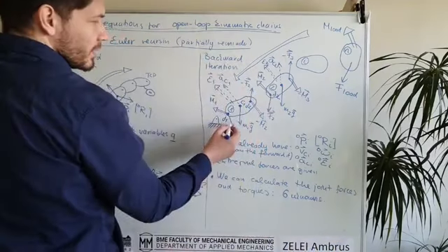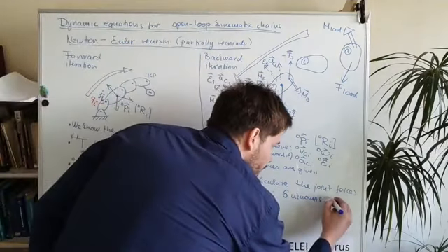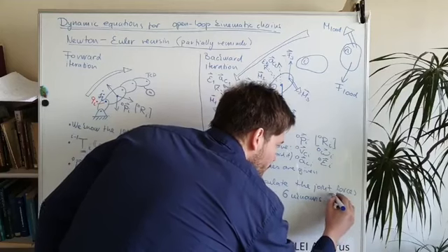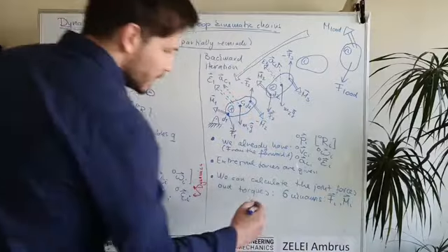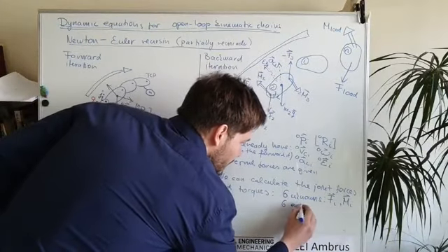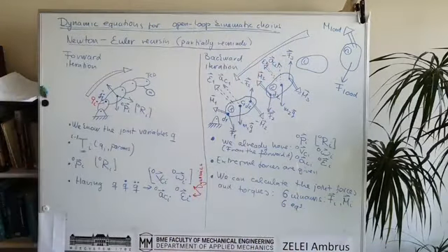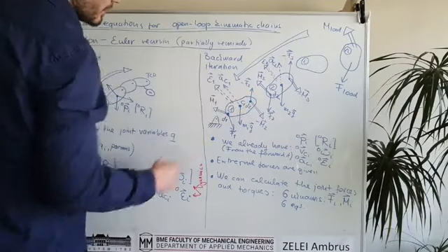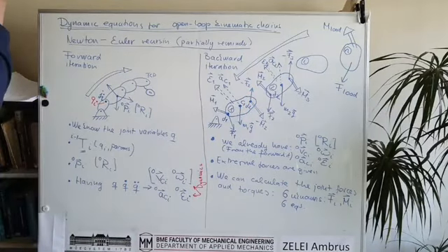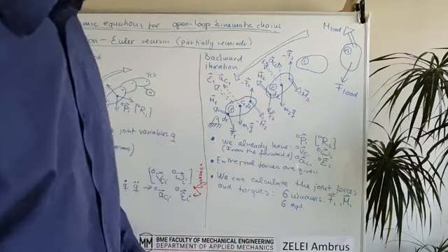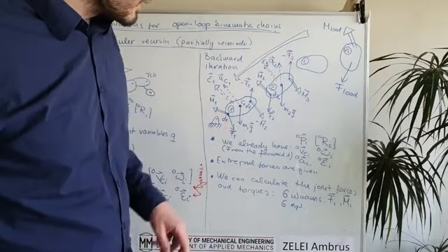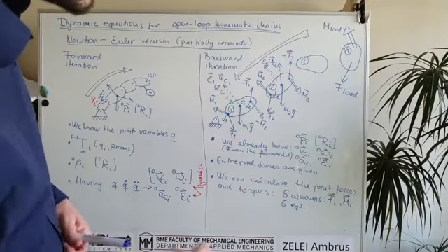So always the corresponding joint torque and force is the unknown. And we know from dynamics that we have 6 equations, so it can be done. So we can create 6 Newton-Euler equations for each body. We will see soon, and we can calculate the joint force and joint torque for each link. Okay, so it is done for each link.